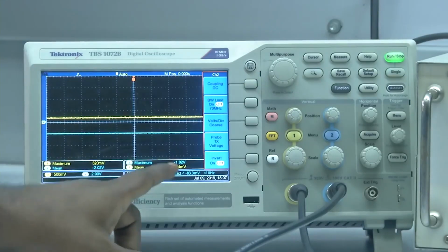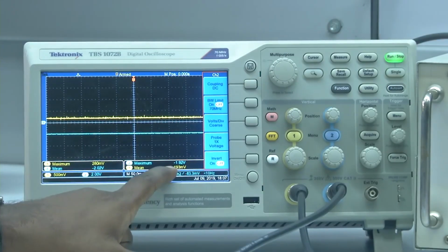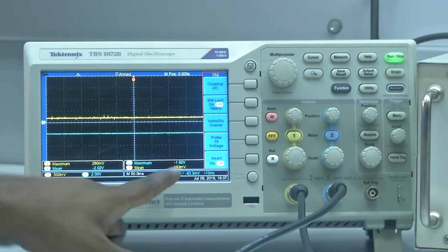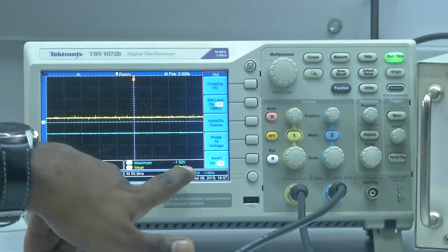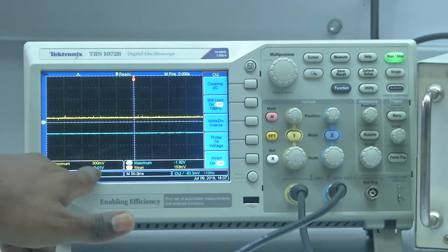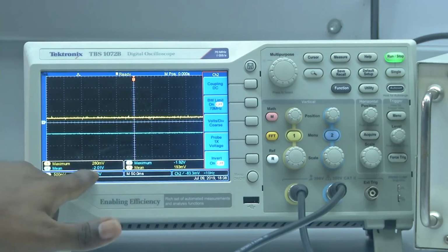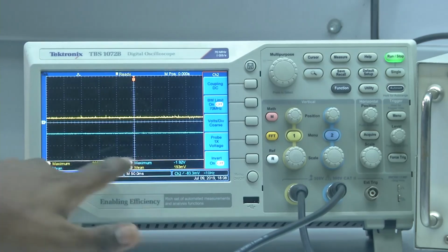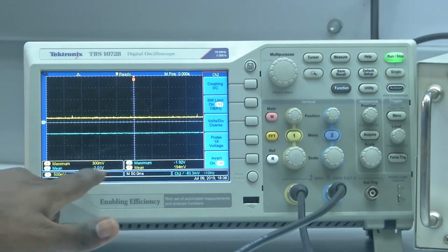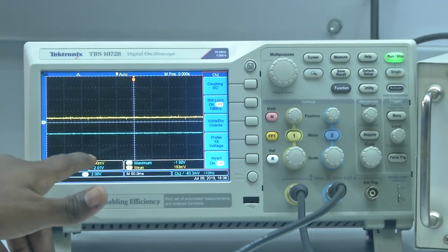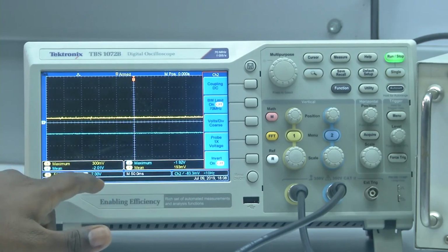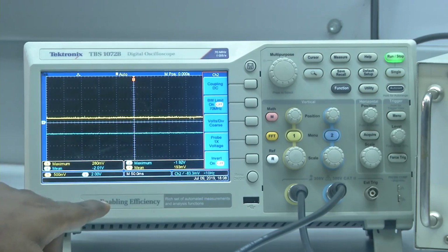So, here if you observe, the mean of input is 193 millivolt, we are getting close to a mean of minus 2.1. If you observe carefully, the input is positive, but the output we are getting is negative, which indicates that because of the inverting amplifier configuration, we will always have a phase difference. Magnitude will be 10 times the input, but the phase will always be different. That is because of our inverting type of amplifier.